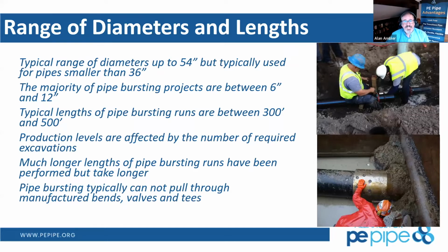It is atypical to burst through valves, but we do have video of bursting through valves. And I will say that the pipe bursting equipment does not care what it's bursting through. And if it does get stuck, then it becomes an unplanned pit. There's not a superintendent on the job site that is not ready to dig an unplanned pit.